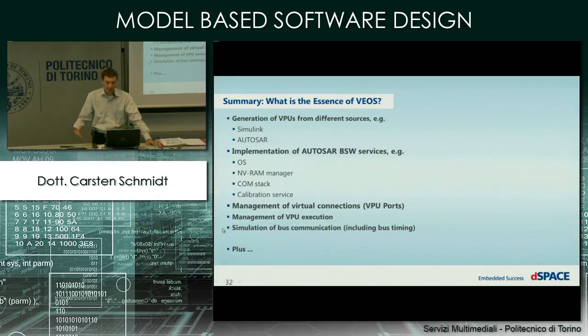And this can be simulated in this virtual simulation too. Then you can, for example, analyze this simulation and see whether the bus communication works or whether you have too high a bus load and maybe you have to do something to fix that. And you can simulate that too. So all these are features of VEOS, and in this way VEOS enables you to do quite realistic simulations.